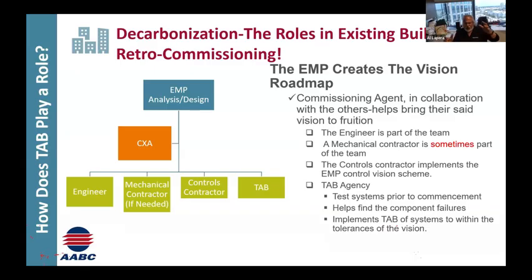Well, I don't remember exactly, I want to say there were eight different air handlers, but four of the air handlers, based on the cut sheets and schedules from the original design, were supposed to produce 40,000 CFM. Four of the eight were supposed to do 40,000 CFM. When we tested them, they never got beyond, I want to say, between 26 and 28,000 CFM. Well, the first thing I did is I went to the owner and said, hey, here's what we found.